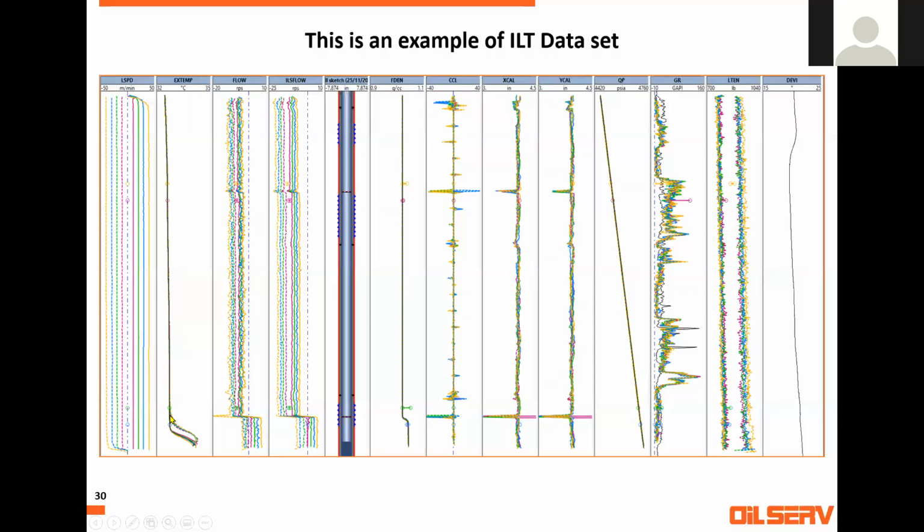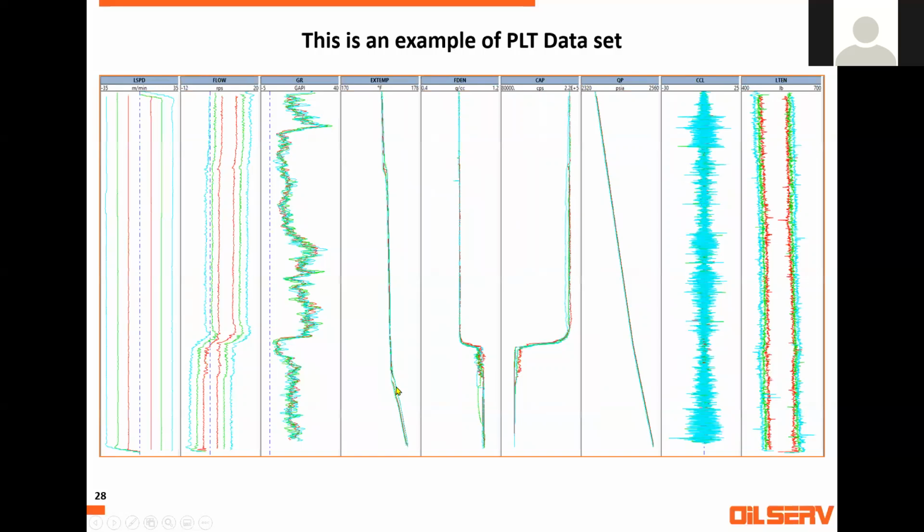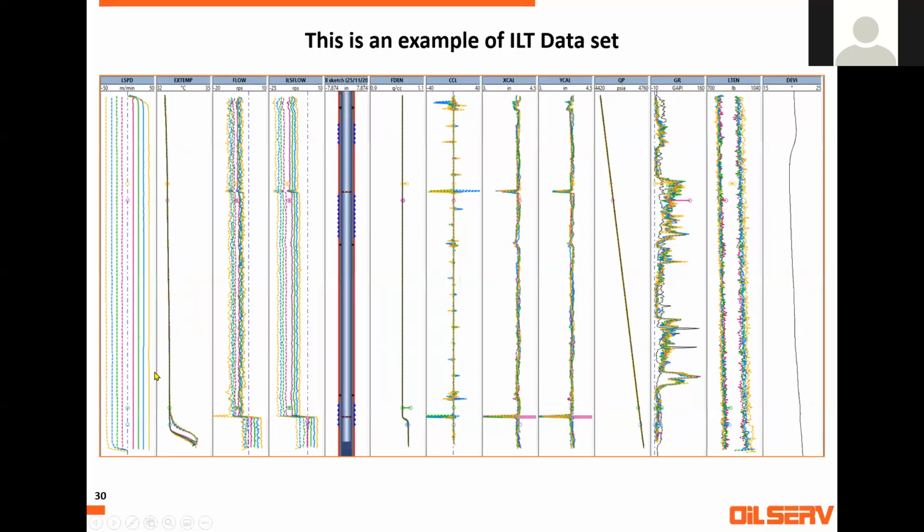What is the temperature difference here? Can anybody see the difference? You see, this is the producer temperature. It's going, and there is some cold entry here because there's some production here, and there's some cold entry. So you see there is a change in the temperature. But for this temperature, it's flat, and very minor, only 32 degrees. I'm not sure whether in Australia it is Fahrenheit or Celsius, but this is a very low temperature. The reason is that you are using injected water from the surface, so everything is at the same temperature.